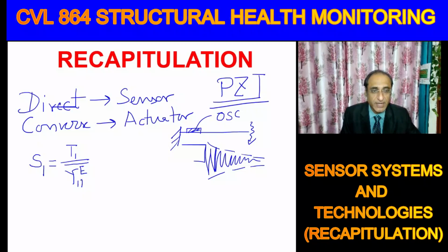E indicates that this has been measured under zero electric field. And how do we ensure zero electric field? We do short circuiting of the top and the bottom electrodes, and this ensures that there is no net electric field. So this is one part, and the other part is that strain is produced not just by stress but is also produced by the application of electric field.